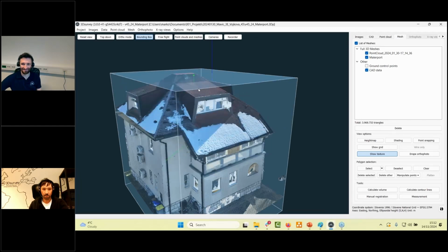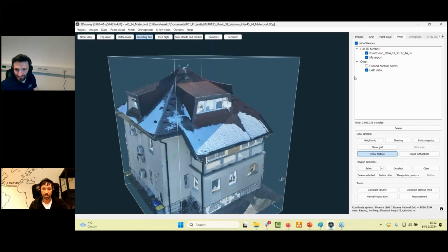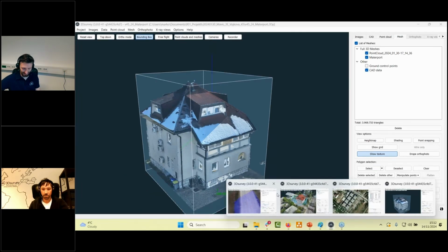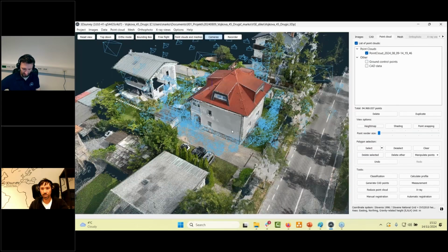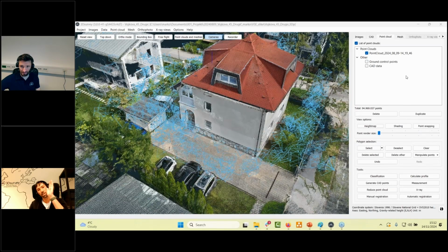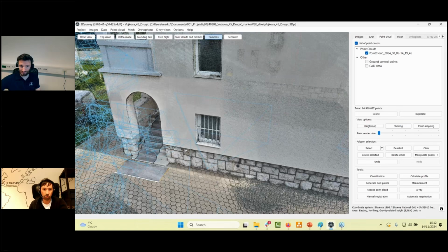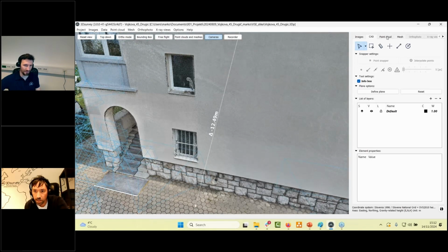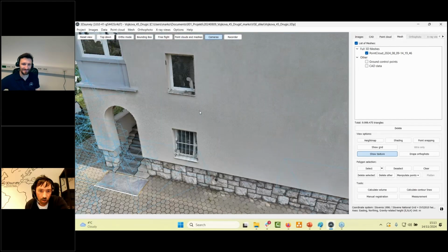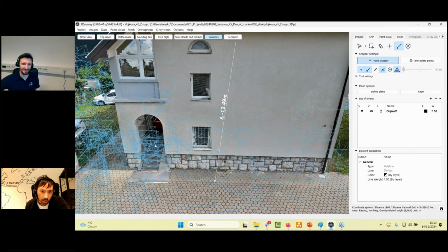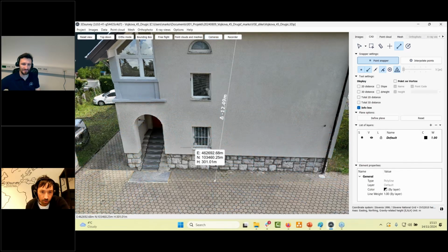Yes, Mattia, what was the next question? Yeah, sorry. What is the best way to draw a building wall with CAD tool? Okay, building wall. So you have more options. One option is to use a custom plane orthophoto or side orthophoto, and then draw in third-party software this building wall out of it. Another option is to draw it in a CAD tool. Let me just prepare it in 3D survey. Of course. So go to the CAD module and draw it, turn on the cameras and draw it like that.